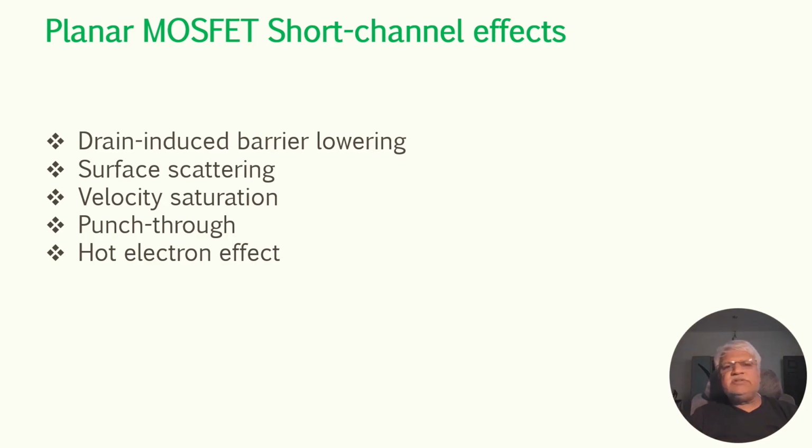For many generations, the switching speed and hence the performance of the transistor could be increased by shrinking the gate length and by applying the scaled voltage to improve the channel mobility. However, as we know, in long channel MOSFETs the gate fully controls the channel.